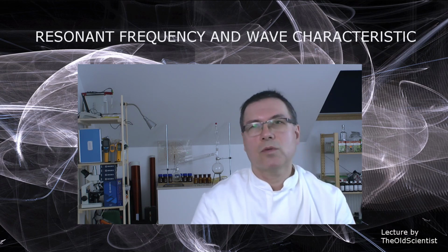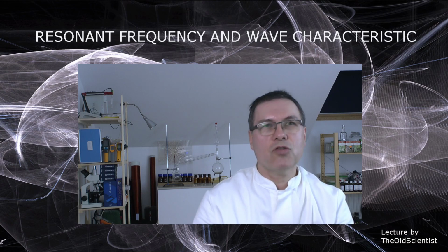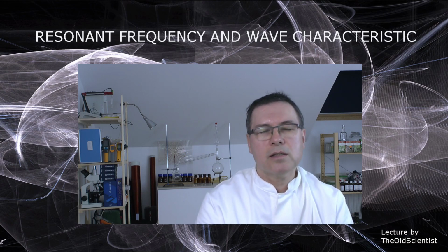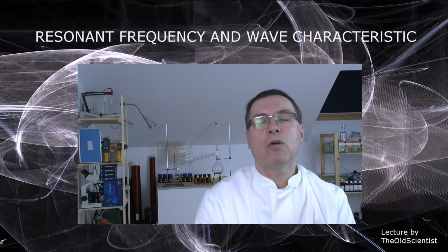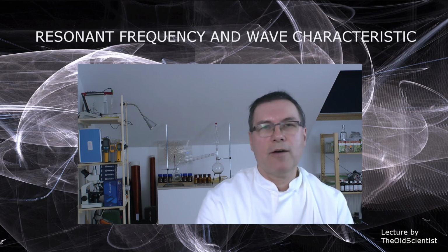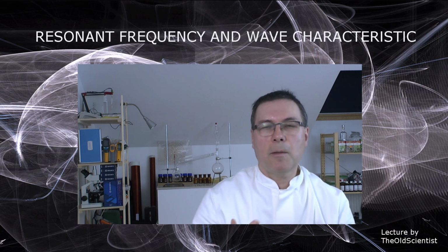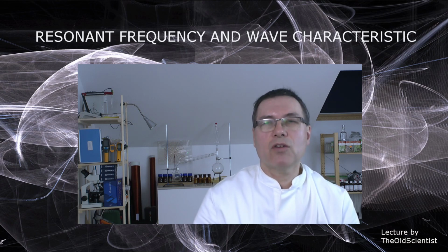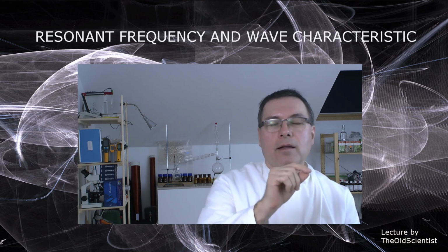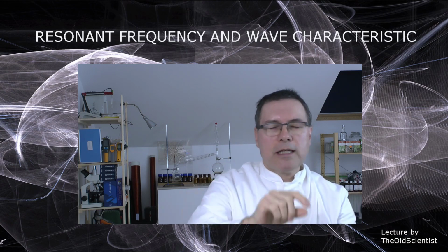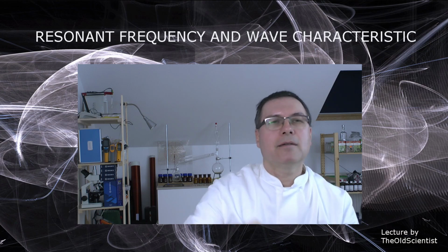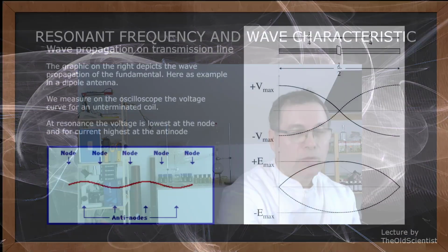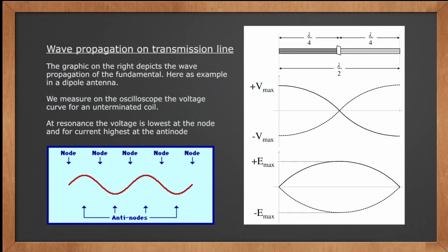On a coil, technically the only way you can get energy transferred between air coils is via resonance. However, the problem in resonance is that you have peak values along the line, since your Tesla coil is a transmission line where waves get exaggerated or extended, as we see in this video. Let me show that again to you. It will be shown here at this node. So if this appears on the coil itself, you have peak values.